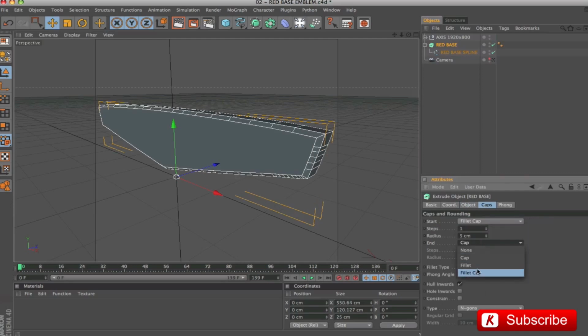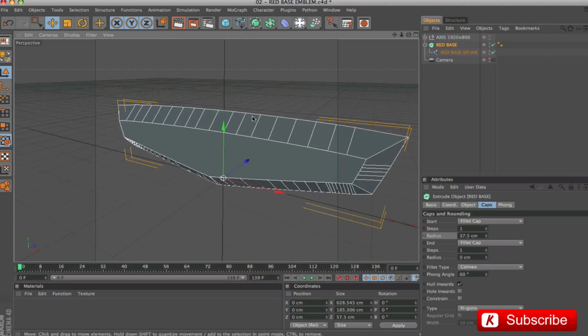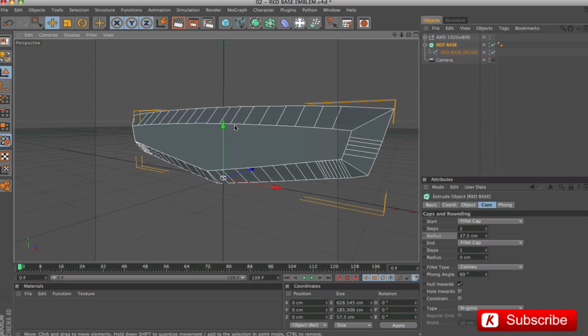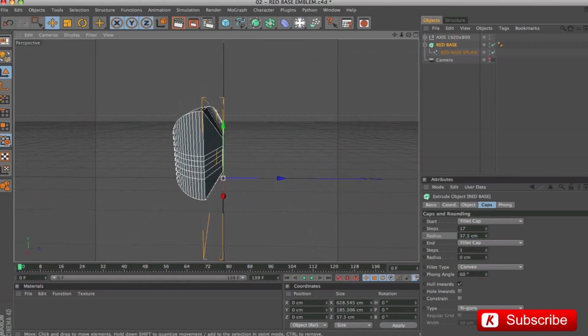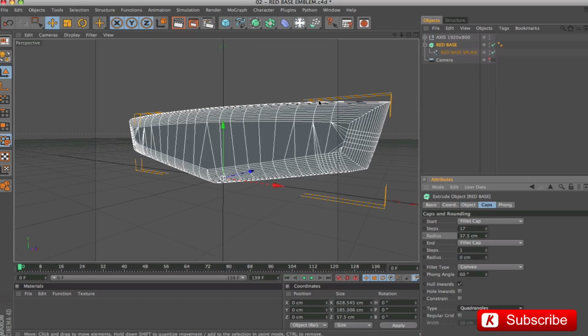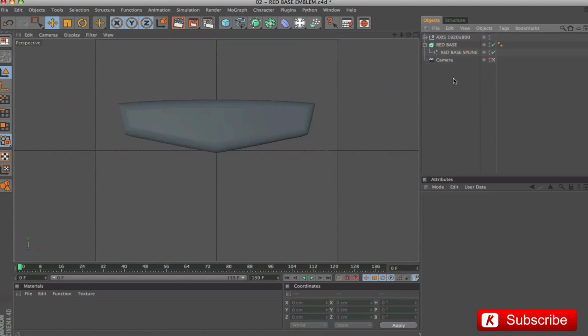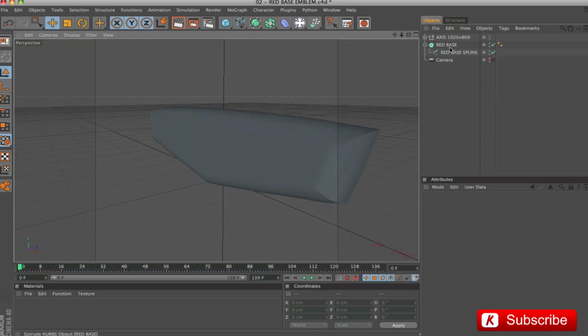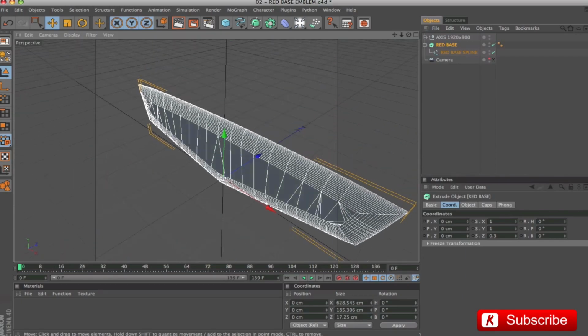We apply a fillet cap, with a radius value of 0. While for the fillet cap start, radius to 37.5, to obtain a rounded profile. Set 17 steps, in convex mode. Finally, in the front extrude, use quadrangles mode. We can see the result immediately by applying the Z-scale value 0.3. Here's the result. Simple, and cool.